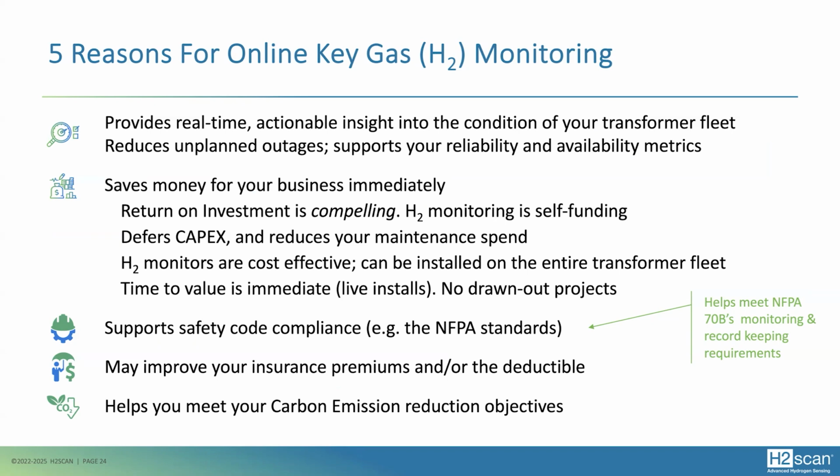We spoke earlier, hydrogen monitors are very, very cost effective. Remember, one of the biggest objections is that it's too expensive. Well, yes, a large multi-gas is expensive, and it's kind of hard to justify putting it onto a smaller distribution or industrial transformer. But hydrogen monitors are very cost effective, and they can be installed on an entire fleet. And your time to value is immediate. On average, it takes 1 to 2 hours to install and start seeing data from them. There's no requirement for outages unless your standard work practice requires that.